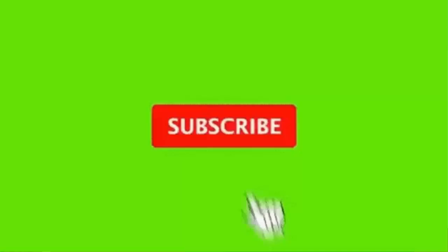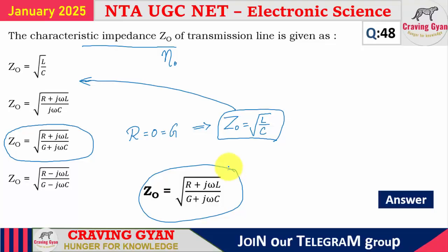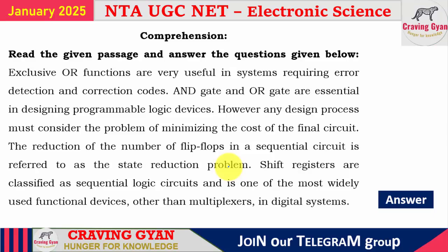So the characteristic impedance Z0 of a transmission line is given as the square root of (R + jωL) divided by (G + jωC). Very, very important. 49th question, again this question is based on logic design or digital electronics.